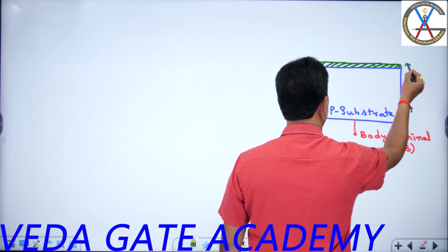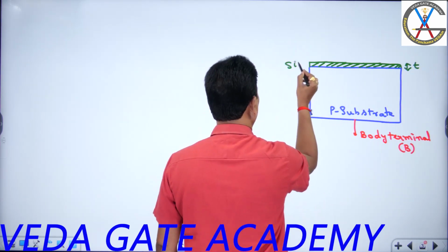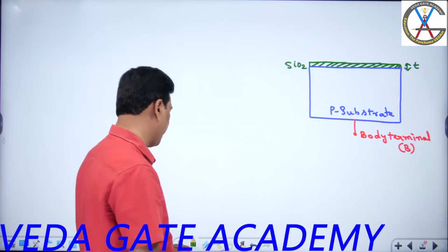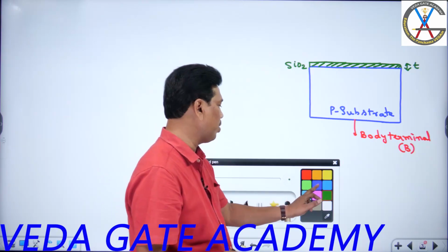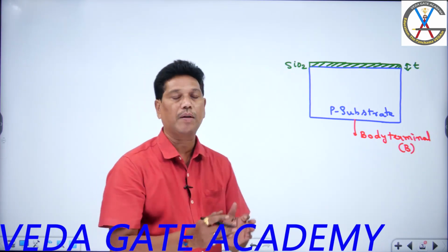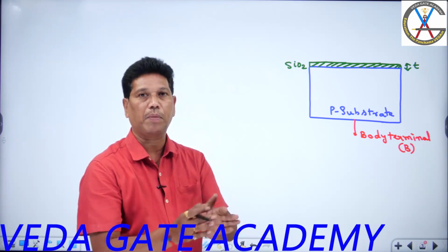Whose thickness is T, I can call it very, very thin, students. And this oxidation coating can act as a dielectric medium. Over which, what will I do, students? Over which I can keep a polysilicon of P plus or N plus material that can act as another electrode or metallic plate, you can call.